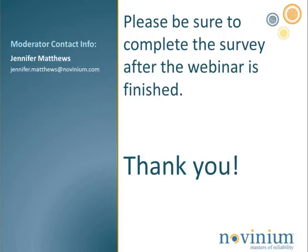When you mated the interface, it does migrate out, as I mentioned. There was a University of Connecticut study done several years ago. It's probably easy to get a copy of that study, but the pressure actually forces the grease out. Now, the thin greases that I mentioned, when someone uses a very thin grease, it migrates out very easily. The thicker greases, the ones that are supplied today, actually meet the performance criteria that is now in IEEE 386. And it's a pretty severe criteria.